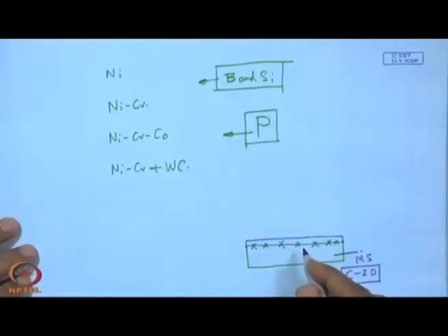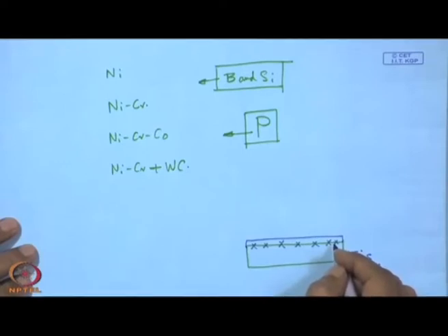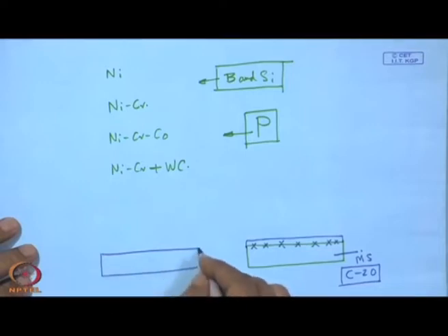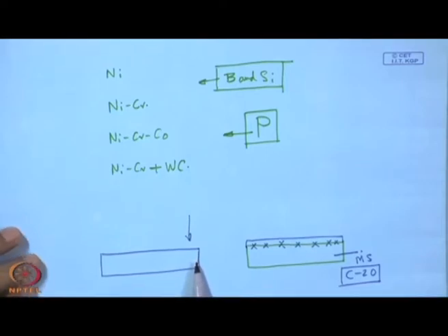So, this is number one, and number two is that during deposition, at the point of deposition, the nozzle comes and it is going to hit this substrate. So, there is a little bit of heating and immediately it starts spraying the material. Though the temperature is not very high, one thing we have to make a note of is that this process is conducted in open atmosphere. That means it can be carried out in a welding shop, or even in a fabrication shop in open atmosphere.